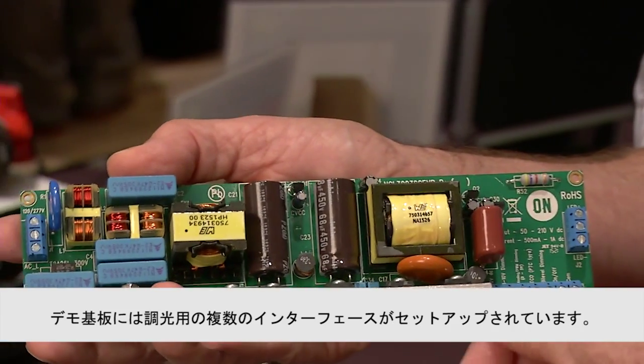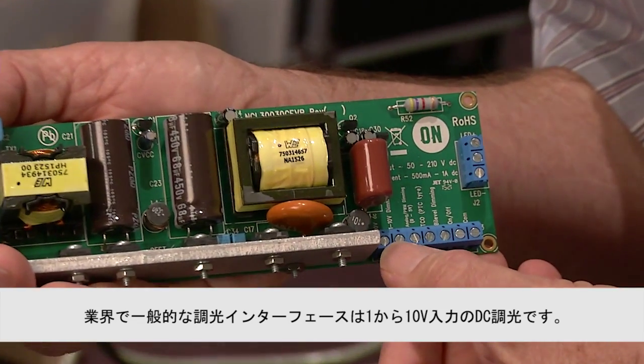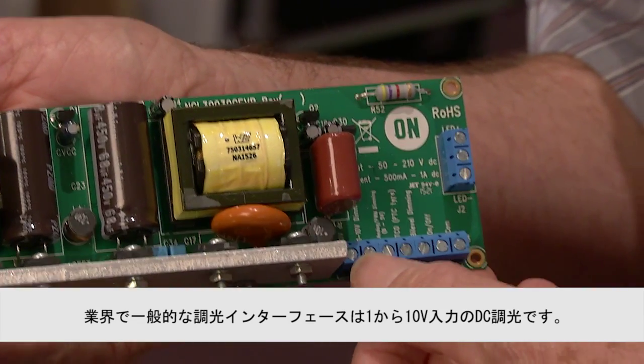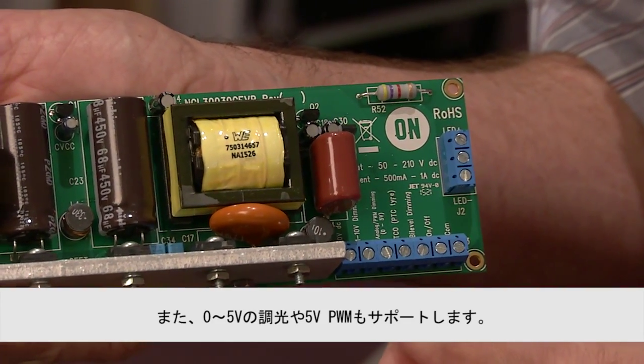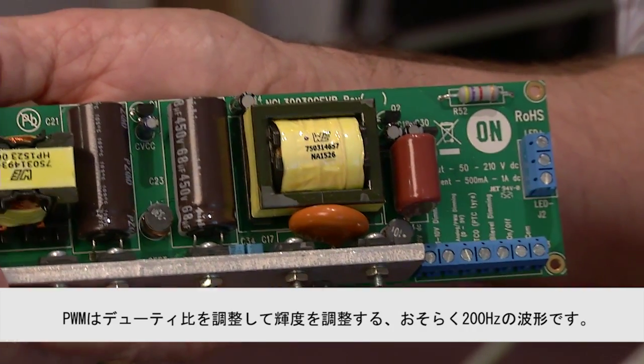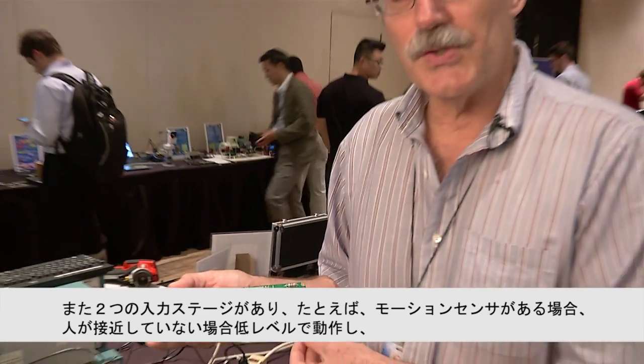The demo board has been set up with multiple interfaces for dimming. A very standard dimming interface in the industry is a 1 to 10 volt DC dimming. There's also 0 to 5 volt dimming supported, as well as 5 volt PWM. The PWM may be a 200 hertz waveform where you adjust the duty factor to adjust the brightness. It'll also support a 2-input stage. For example, if you had a motion sensor, it would operate at a low level when there is no activity, and whenever there's activity in the area, it would step up to full brightness, therefore saving power whenever there aren't any occupants in the area.